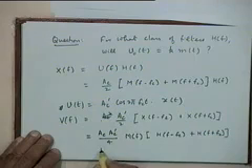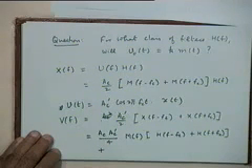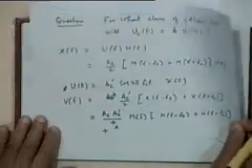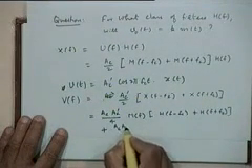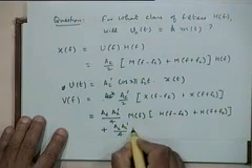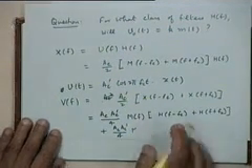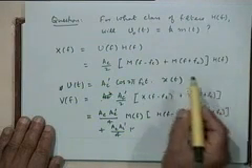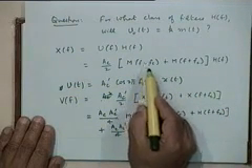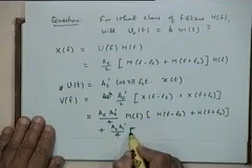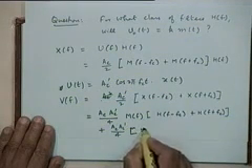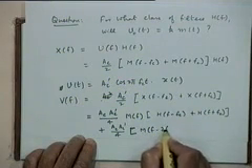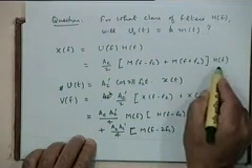What about the two 2fc terms? Same amplitude Ac prime upon 4. So what will you get here? You are shifting this to the right by fc, right? So this will become M of f minus 2fc. So I don't think I'll have a common factor now. M of f minus 2fc, and what will be the corresponding H factor?